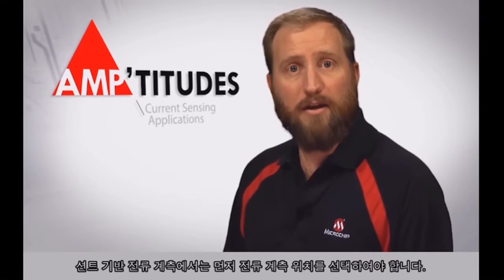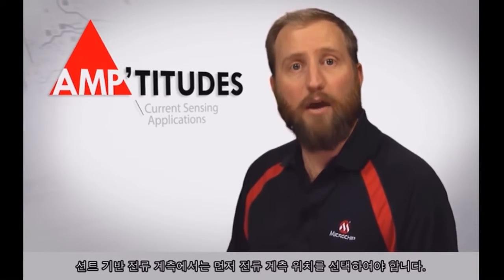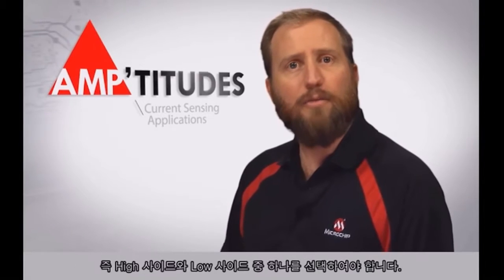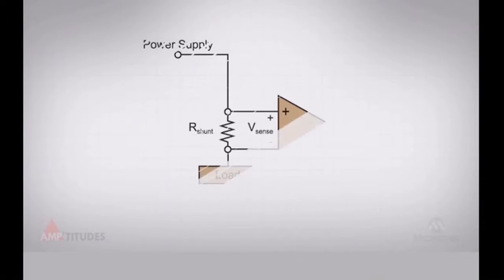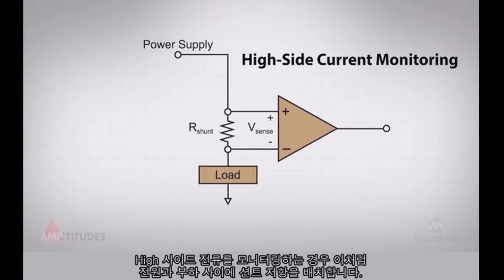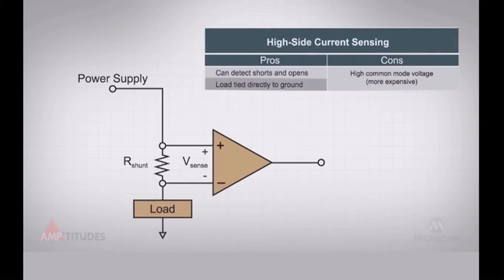For shunt-based current monitoring, the first question that must be addressed by a system designer is where to monitor the current. There are two basic options, high-side and low-side current monitoring. For high-side current monitoring, the shunt resistor is placed between the power supply and the load, as shown here. For low-side current monitoring, the shunt resistor is placed between the load and ground, as shown here.